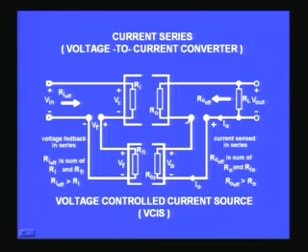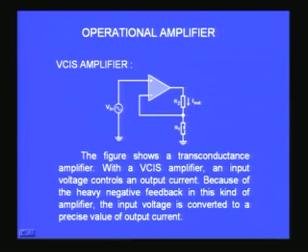And now let us try to look at the circuit based on this. So what you see on the screen is a very simple op amp voltage to current converter. In the feedback, this is a negative feedback. You can see that you have an R1 and an R2. So whatever current is flowing through R2 and R1, a potential divider, this voltage is applied here in series with the input voltage, and therefore this is exactly the same as what we discussed a moment ago.